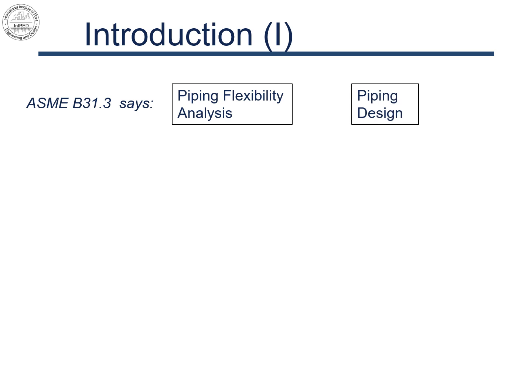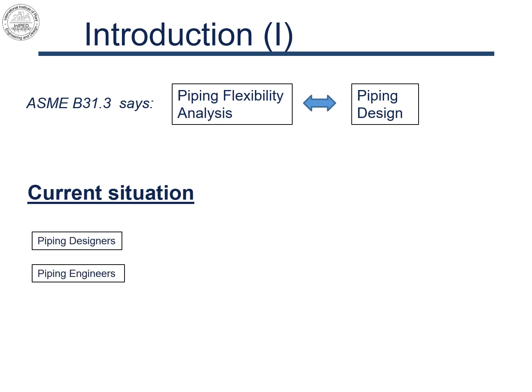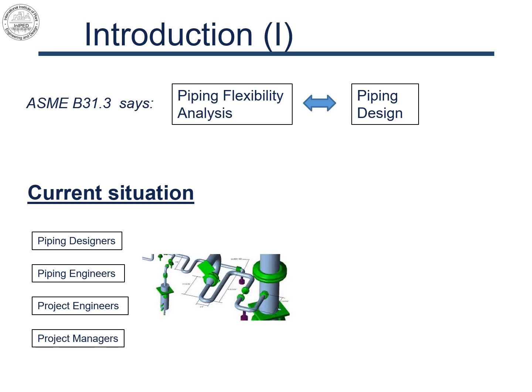ASME B31.3 is clear on how piping flexibility analysis, or stress analysis in common terminology, is tied to piping design in terms of required educational and related practical piping design experience. It does not, however, advise on the level of experience, familiarity, or understanding that piping personnel not directly involved in stress analysis, from piping designers and engineers to project engineers and project managers, should possess in relation to piping flexibility analysis or stress analysis issues.